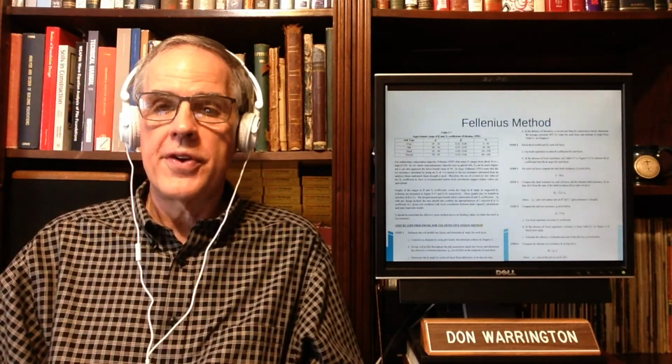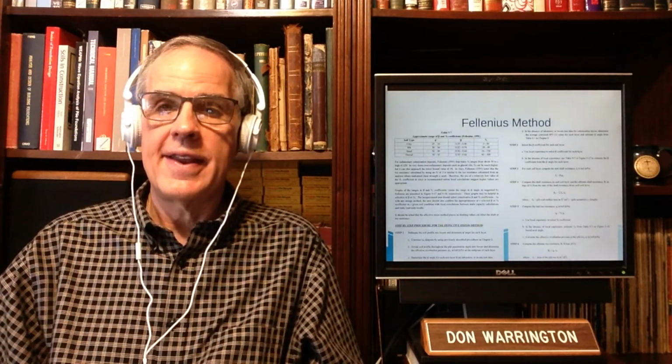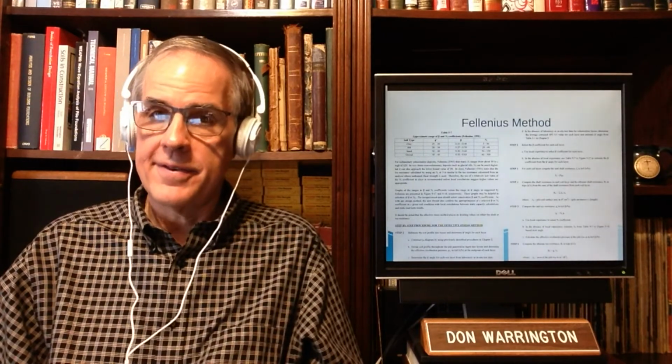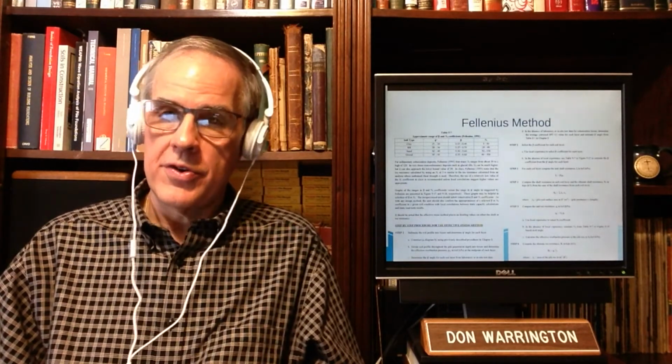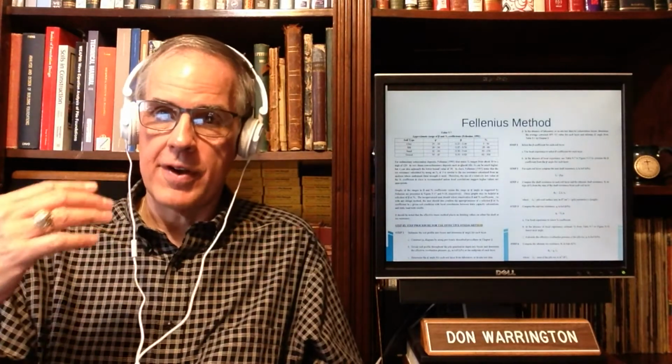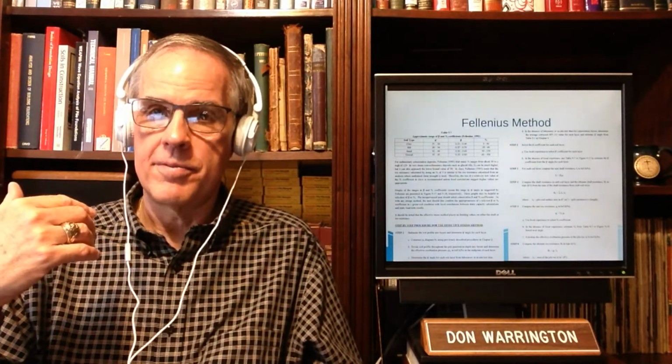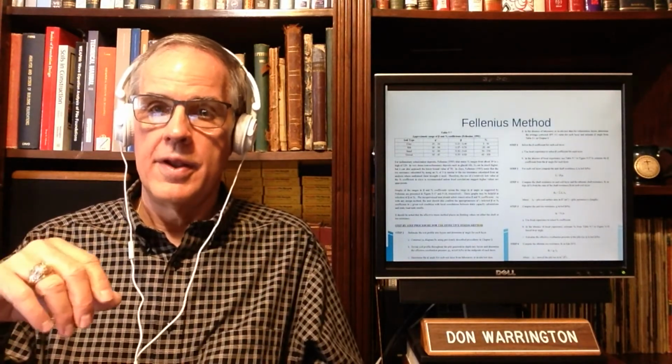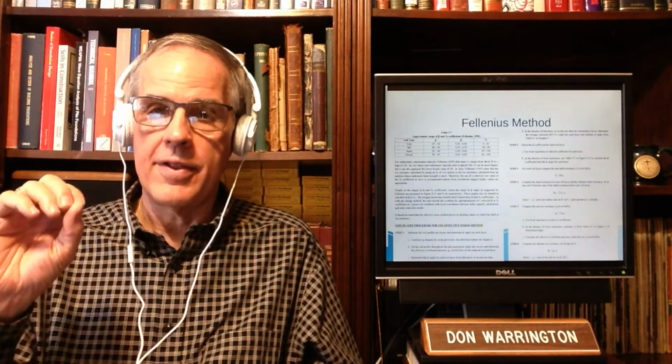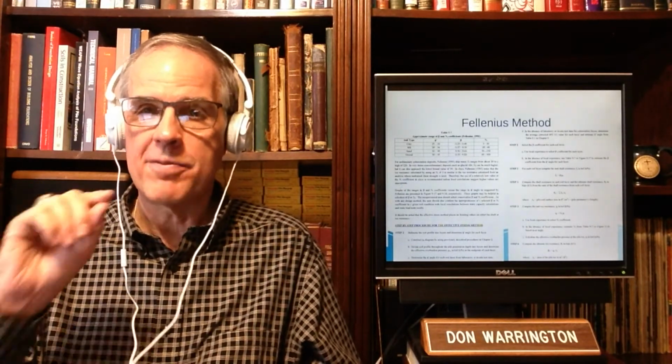The effective stress for any layer is taken at its center. Obviously, if you divide up into more layers, you get more effective stresses, and you might get a little bit better profile of what's going on. But irrespective of how you divide it, that's little fs for that particular layer.